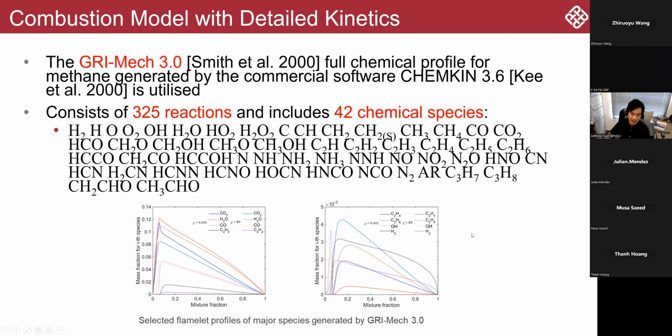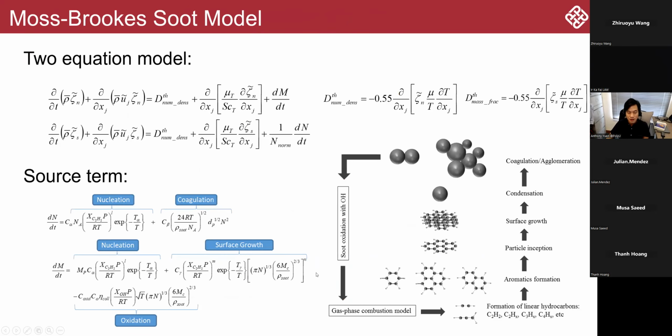So now we can really look deep down into the toxicity formation, because if we consider the detailed chemistry, we can look into even HCN, the NOx product, and so forth. And here is just some example of what the detailed chemistry can do. Not only does it benefit the toxicity prediction, now we can really look into the detailed formation process of soot.